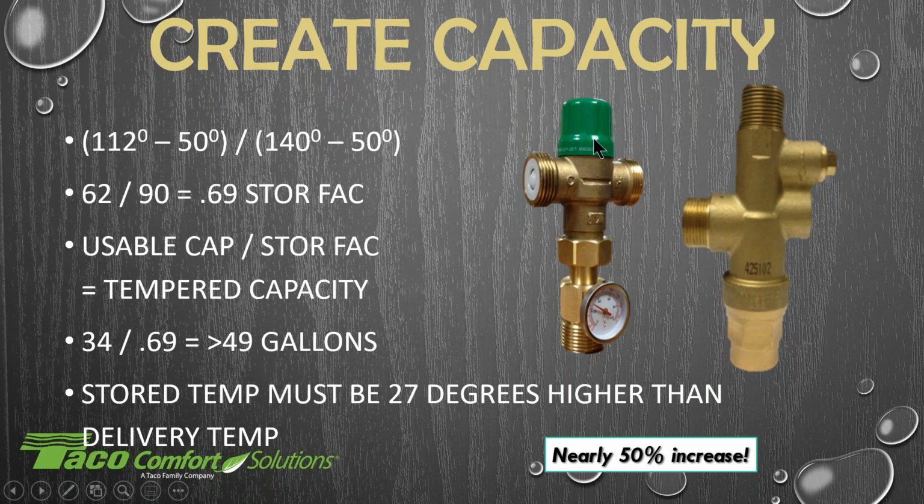And depending upon the valve that you're using, the cap is the tool to do the adjustment. You don't just turn the cap, it doesn't do anything. You actually pop the cap off. If you have a valve that has a triangle shape indented into the top, you take the cap off, turn it over, and you can do the adjustment of the valve. We also have other valves that are fixed temperature because you're not allowed. They are set and fixed at 120 degrees by code. Those standards say it's non-adjustable, you can't increase the water temperature itself. So like I said, there are different valves out there for different applications and where you are across the country.